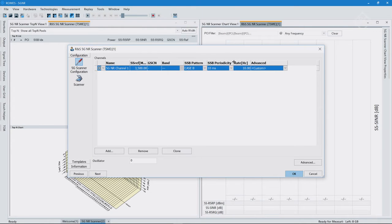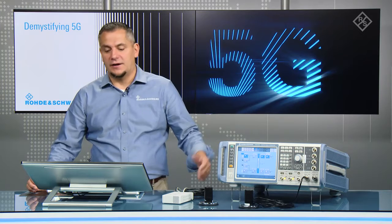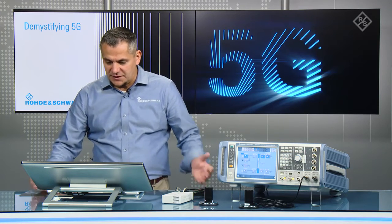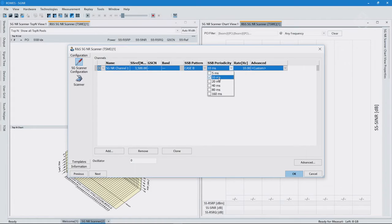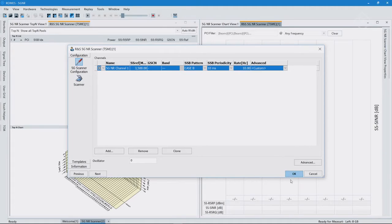And then you have here the periodicity for these blocks, like how often they are transmitted. The standard allows for the options shown here: 5, 10, 20, 40, 80, and 160 milliseconds. In my example, I'm using 10 milliseconds. The default value that the mobile will assume while I'm just switching it on would be 20, so that's something that is set in the standard. But as I said, my example is 10 milliseconds. So this is the configuration where I'm telling the scanner which frequencies to scan for.